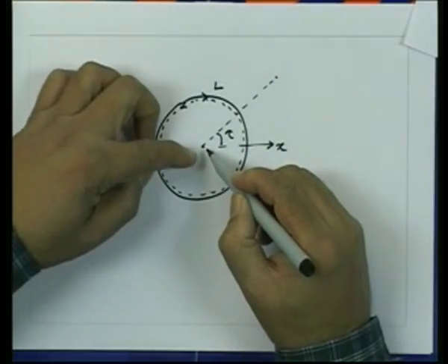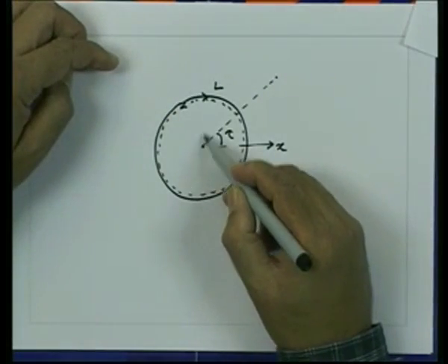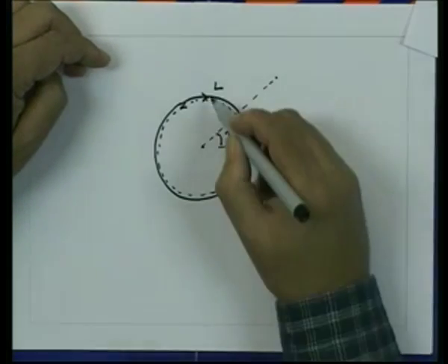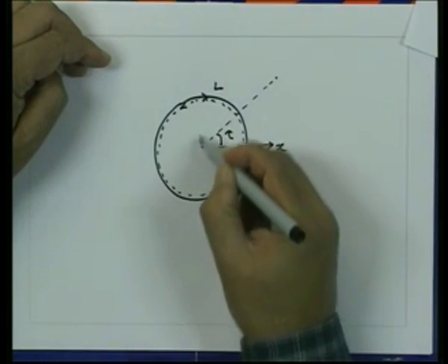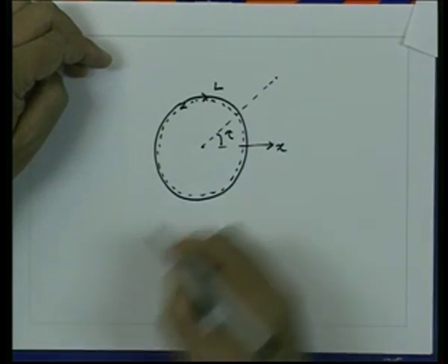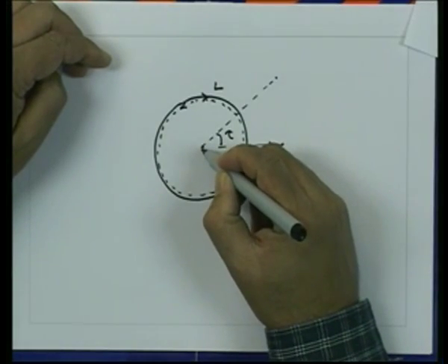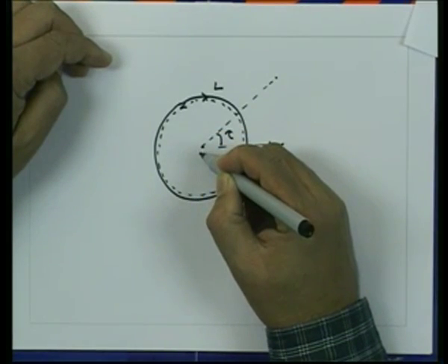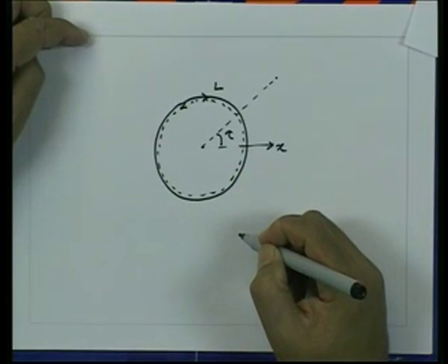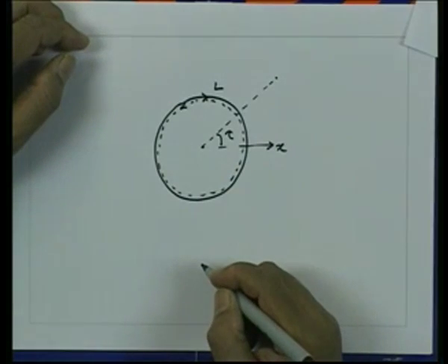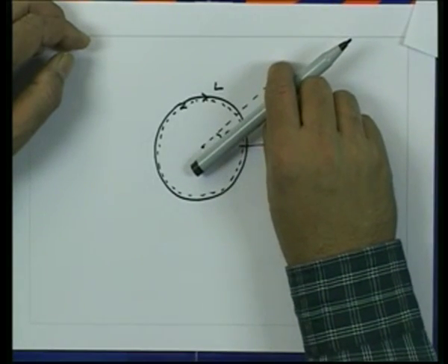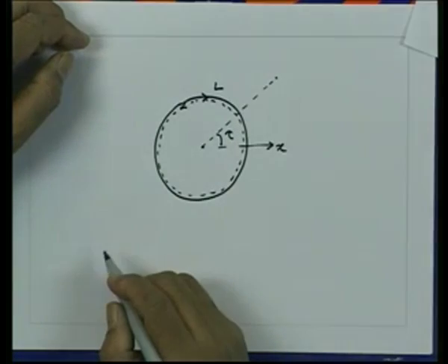Now, since these two vectors are going to make always equal angle with respect to this line, as they rotate, this vector will rotate this way, this vector will rotate that way. The component of the vector which is perpendicular to this line will be of equal magnitude and in opposite direction. So, it will always cancel out, and as the vector rotate, the component which is in the direction of this line will vary.